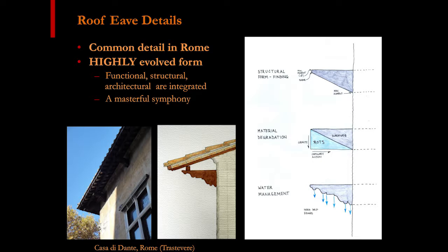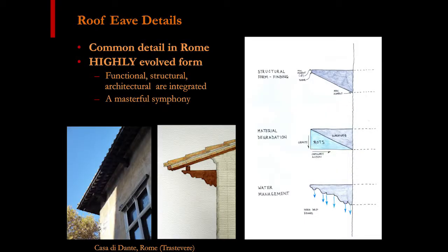And then if you think about this angle, even in a 45-degree wind-driven rain, which is pretty severe, this never gets wet. So that's how they made pine work in this rainy, humid climate, untreated, unpainted, and never rot: A, keep it so it almost never gets wet. It takes almost a pure horizontal rain to even get this wet. And then when it does get wet, you get that water off it very quickly. And then by having it unpainted, I think it's an advantage in terms of the drying potential. It dries out really quickly, just like an untreated cedar shingle, particularly up at this height where the wind's really whipping by and past all these buildings. So that's how this has survived for all these years and done so well.